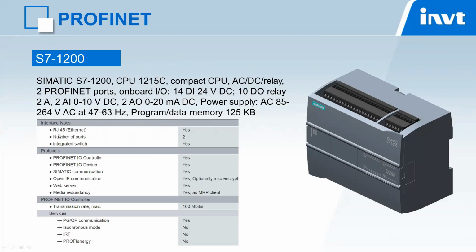This PLC includes two RJ45 Ethernet ports. It supports Profinet I/O controller and Profinet I/O device. It does not support IRT, where the response time is 1 millisecond. This CPU only supports normal Profinet I/O, so the response time is 10 milliseconds. The transmission rate is 100 megabits per second.